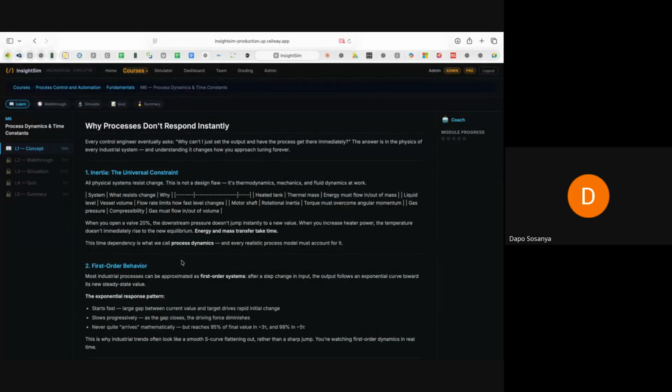So your scan time needs to be planned and well designed, right? Such that even if the PLC takes its eye off that critical transmitter, we will have checked that there won't be any problem within the scan time. Even if the state of that transmitter changes after it has been read, it will not constitute danger to the process within the scan time. Does this make sense to you?